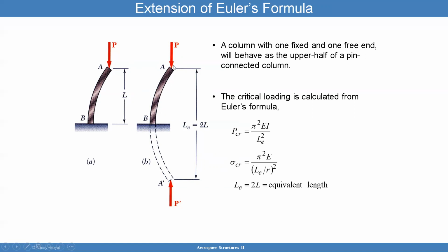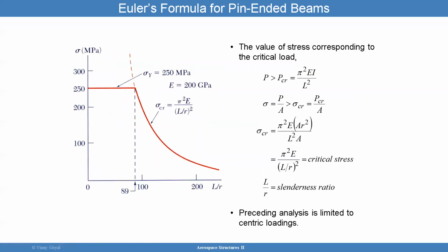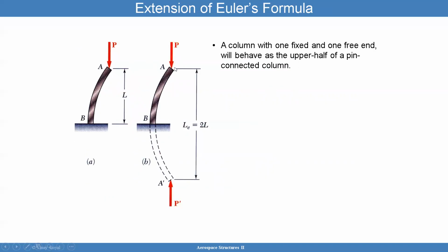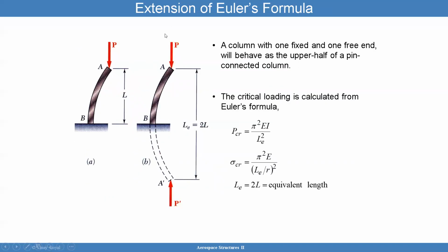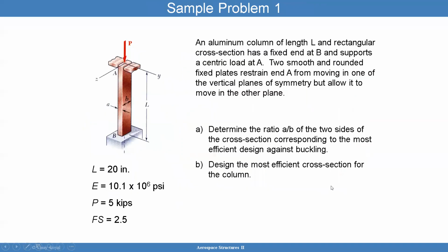In this case, I'm looking at one free end, the solution for one free end. Here I was looking at a solution for the pin situation. Here I'm looking at the clamp-free situation. You can look at it as eccentricity as well, but that's not the point. The point is that you can actually derive the solution based on the pin-pin condition. Here is an equivalent length if you want to look at various configurations, like pin-pin, for example, but here you have pin-clamped, and this is keeping the slope fixed, and then the other is completely fixed, clamped.